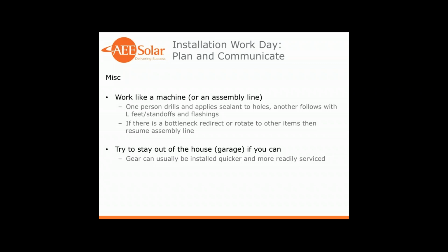So one other area is we typically recommend installing the equipment outside of the house, in the exposed or easy to access areas. We find that it's easier to do the initial installation, and it helps in the future if any service or repairs are required. And the truth is, in garages, sometimes customers will find that the inverter or different equipment is just a great place to put their junk on top of. And you want to minimize that as well, because the equipment has ventilation needs. So we try to keep our gear outside whenever possible.